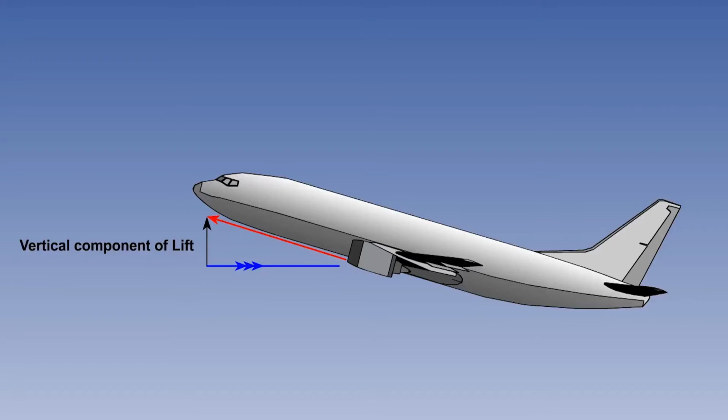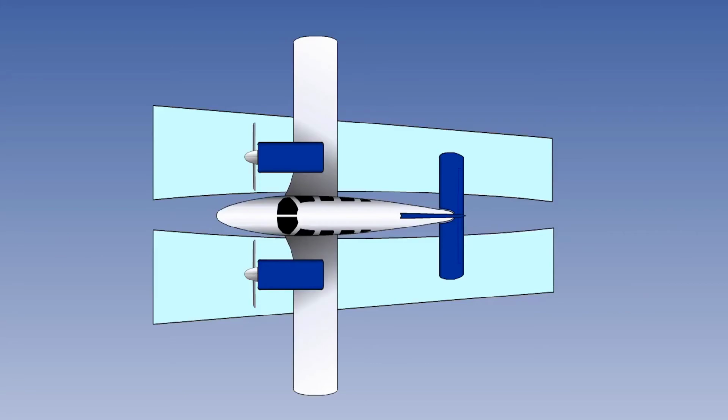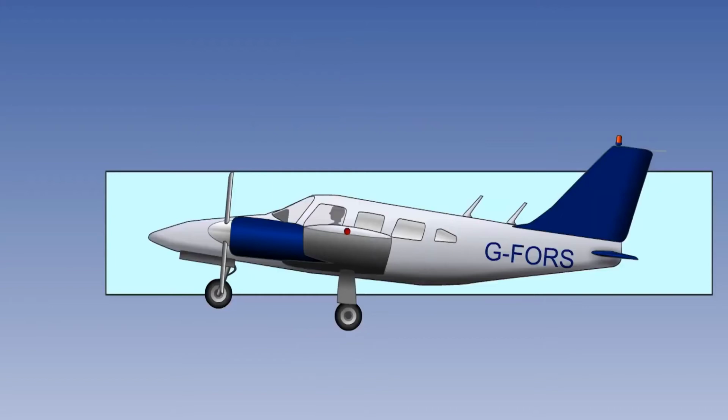The most important factors in this situation are engine type, propeller or jet, thrust-to-weight ratio, and the inclination of the thrust vector at CLmax. With propeller-driven aircraft, the slipstream velocity behind the propellers is greater than the free stream flow, depending on the thrust. Thus, at low IAS and high power, the dynamic pressure within the slipstream is higher than that outside it, and generates more lift than at zero thrust. The lift at any given IAS or angle of attack will be significantly affected.